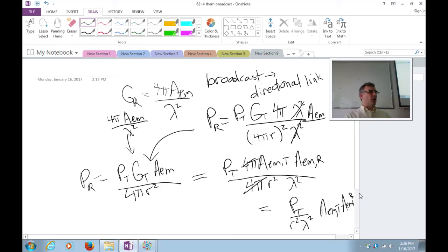Oh, this is satellite communications. Who was using millimeter waves long before it was cool to talk about in the cellular world? They've been using millimeter waves for decades in the satellite industry, because if you want to overcome tens of thousands of kilometers of path loss just to get to an Earth-based satellite out in geostationary Earth orbit, or even worse, if you're sending a radio wave millions of miles to talk to a rover on Mars, or a spacecraft on Saturn, or Voyager, which has left the solar system completely, at least the inner planets, all of the known planets that we talk about, in order to overcome the enormous amount of path loss, you would like to have two directional antennas that you can point.